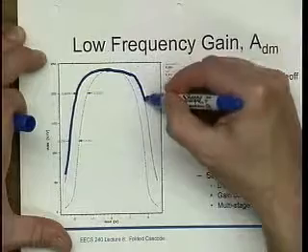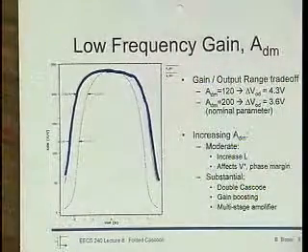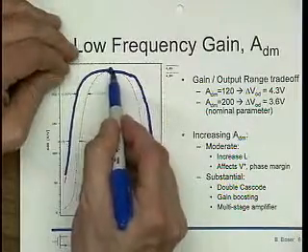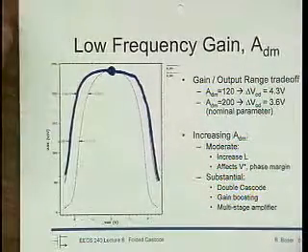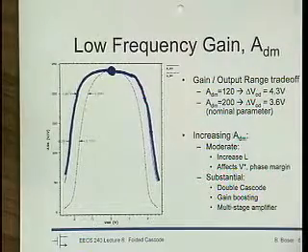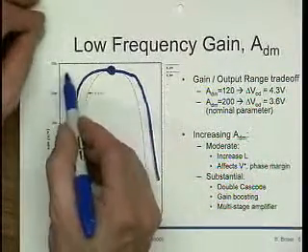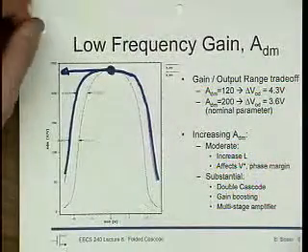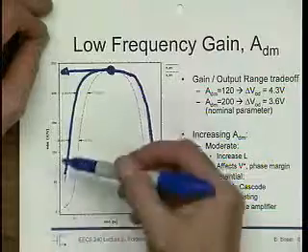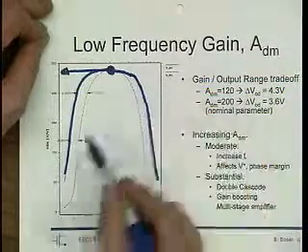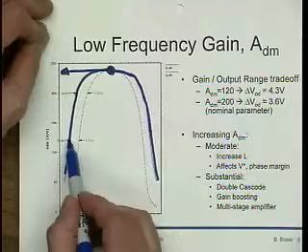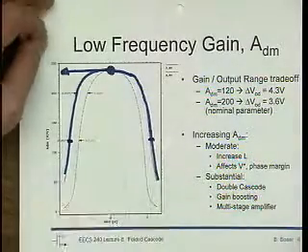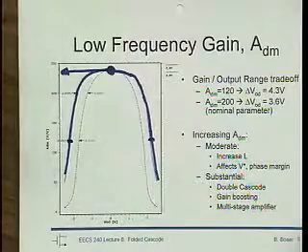Okay, so we actually get a little bit more gain than Spice would make us believe from running just a small signal analysis. But of course, if we run the small signal analysis only for VID equals VOD equals 0, then we are at this point, and that is the maximum and a very optimistic idea. The differential input voltage is just over 2 volts here, so here's minus 2 volts, here is plus 2 volts, so a 4 volt output range in a 3 volt supply, not too bad, right?